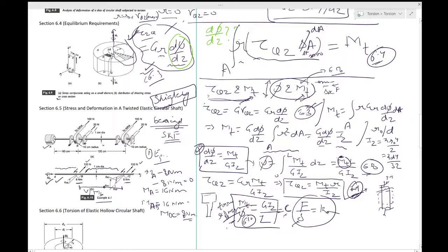For this you might have to draw that, just like you had drawn the bending moment and the axial force diagram for the whole segment, you may have to draw an MT diagram for the whole segment. There you would start from here and make a break over here and another break over there. So you have to take two segments.